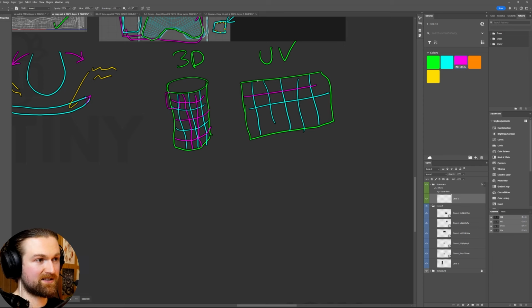So when you insert lines like this, it's going to insert it into the UV, but it's only upon actually adjusting the shape of this, or say for example giving another extrusion, that we're going to start to get issues. What will happen on the UV is it will basically extrude that polygon in space and it won't unwrap it, and then you'll see that we'll have loads of artifacts towards the edges.